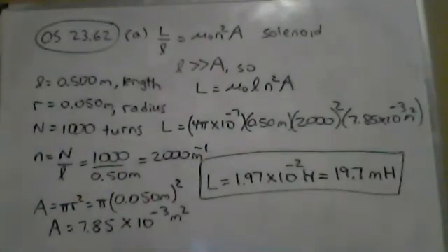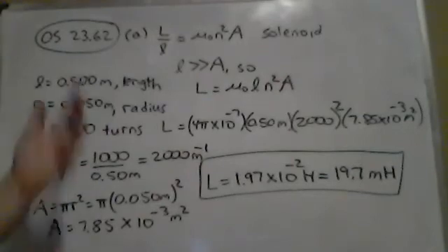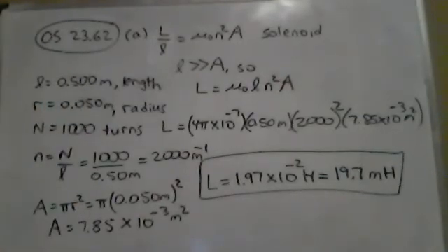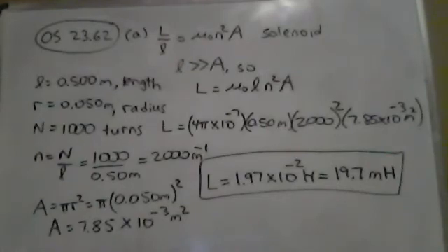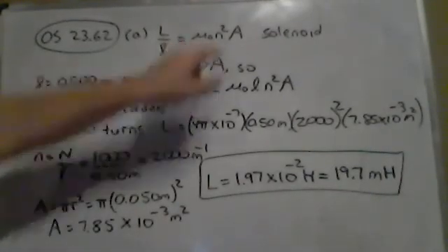That will be the inductance of this solenoid. Now we're going to use this solenoid as an inductor, so it's good that we now know its inductance. That'll be very helpful for calculating magnetic energy. If we take an inductor off the shelf, we now know how to figure out its inductance: mu naught N squared A over l, provided I'm given N. It's quite difficult to count 1,000 turns of wire, so you hope the manufacturer tells you what little n is.